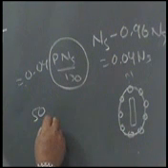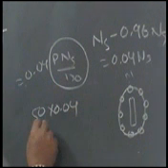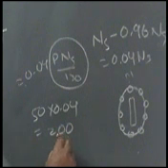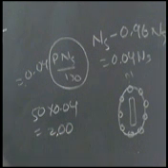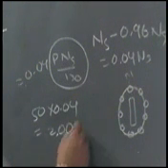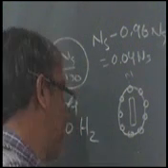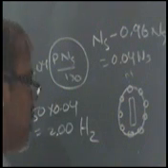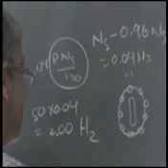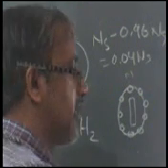This will be equal to 2. That means the current in the rotor will have a frequency of only 2 Hz. It is not believable, but it is true that the rotor current frequency is very low, whereas the stator current frequency is 50 Hz or 60 Hz.